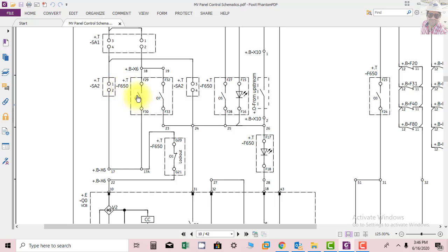In our case, the closing is coming from what is called the breaker management relay, or you can say a multifunction relay. This relay is doing not only protection but also bay control, so you can say it is a bay control protection relay, 2-in-1. When the selector switch is at remote, control is transferred to the bay control relay, and the bay control relay can be connected to a control system. The control system can give a command to this bay control, and then the bay control will do the local operations remotely.